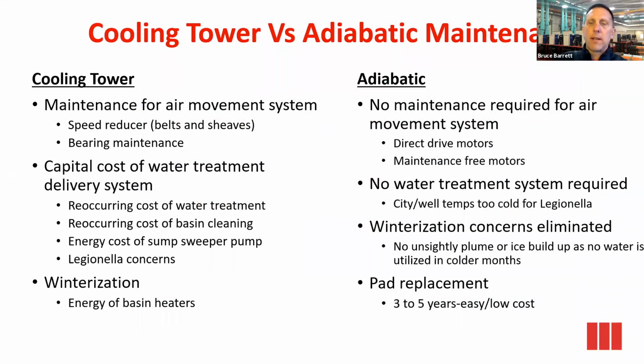And again, just reviewing the differences between a cooling tower and adiabatic. They both work very well. You get a lot of benefits using adiabatic. No maintenance of those tower drives. They're typically maintenance-free motors, EC motors. No water treatment, again, Legionella.